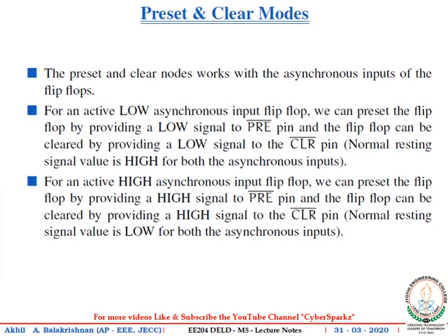Next are the preset and clear modes. The preset and clear modes of a flip-flop work with the asynchronous inputs of the flip-flop. We have already become familiar with the asynchronous inputs, that is, the preset and clear asynchronous inputs. A flip-flop input can be a synchronous input, an asynchronous input, or a clock signal. Synchronous inputs are those inputs to a flip-flop which change the output of the flip-flop with respect to the clock signal, whereas asynchronous inputs are those inputs which change the flip-flop output irrespective of the clock signal. They can change the flip-flop output instantaneously.